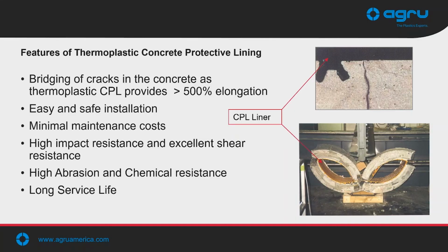Most of the coatings require a very clean, a very appropriate surface for the application of the coating. So in order to reapply more coating, a lot of times it is required that we do a lot of sandblasting or demolition of the existing structure to get down to a good surface to reapply. So there can be significant cost with rehabilitation or recoating these structures, and they can also cause serious downtime or interruptions of processes that we're using that structure for.